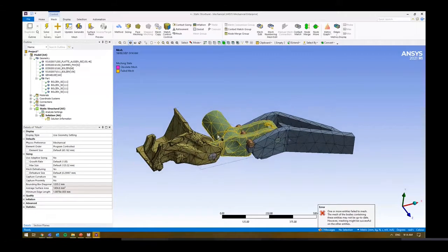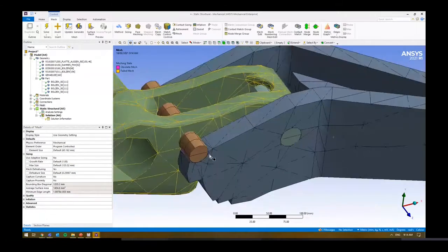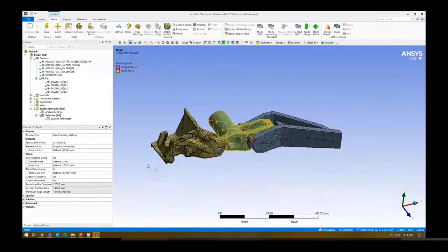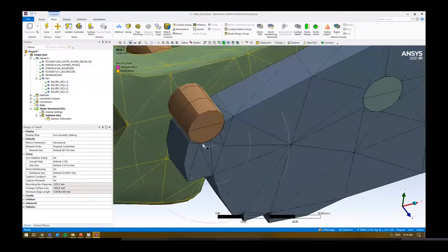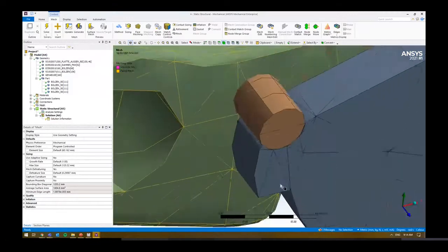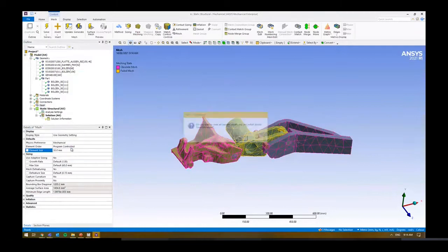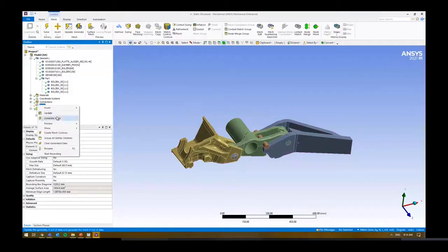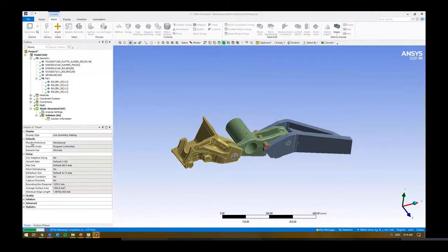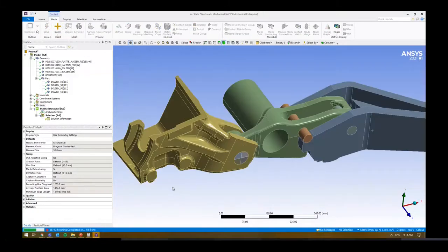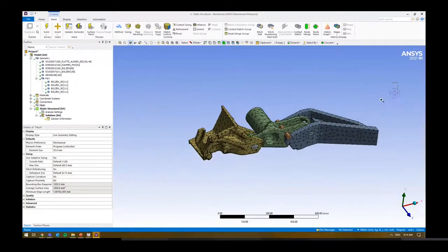You'll notice some of the actual elements are pretty large, like this element size here. Depending on the domain size, it'll try to guess how large the elements should be. You can zoom in. Let's say we want to apply a 30 millimeter sizing. We can clear the generated data and do it again. Again, these are global controls, so based on these controls it'll try to determine what an appropriate mesh might be. We'll let that generate real quick. Yeah, so you can see what's happening here.